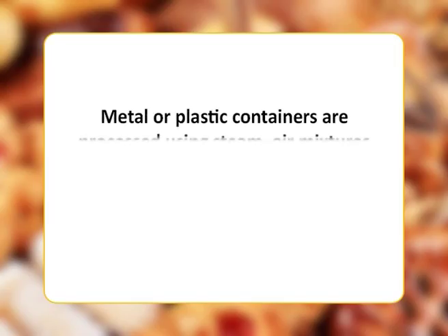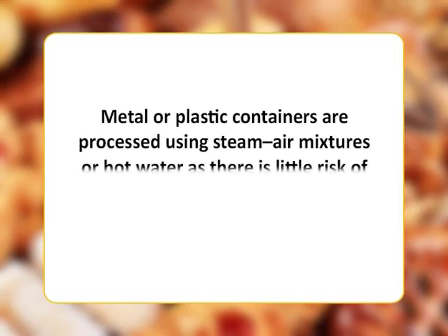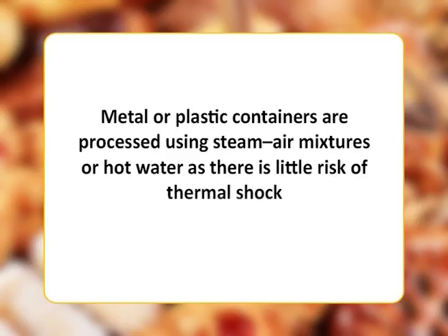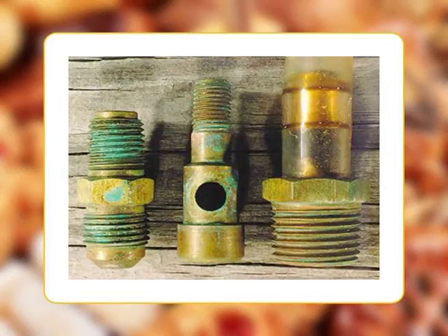Metal or plastic containers are processed using steam air mixtures or hot air as there is little risk of thermal shock. In all cases, the food is cooled to approximately 40 degrees in order to evaporate surface water and therefore minimize external corrosion to the container or cap and to accelerate setting of label adhesives.